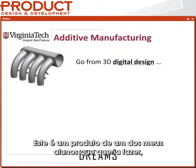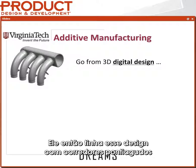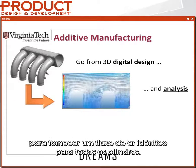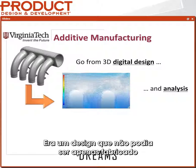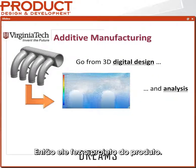This is a project by a student of mine who wanted to make directly his intake manifold to the engine. So he had this design which had tapered runners to provide equal airflow to all cylinder heads. It had a tapered plenum. It was a design that just couldn't be manufactured with traditional aluminum extrusion and welding. So he had designed the product.